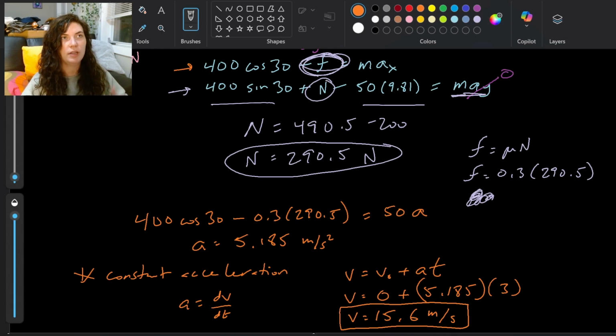All we're doing is creating these relationships: making a free body diagram, making the kinetic diagram, relating force to mass times acceleration. We're having to find all of those multiple forces, break them up into components, find our various accelerations, find those in the kinetic diagram, and then we can go back to our kinematics and solve for anything else that we have left to solve. Let's take a look at a little bit more complicated example.